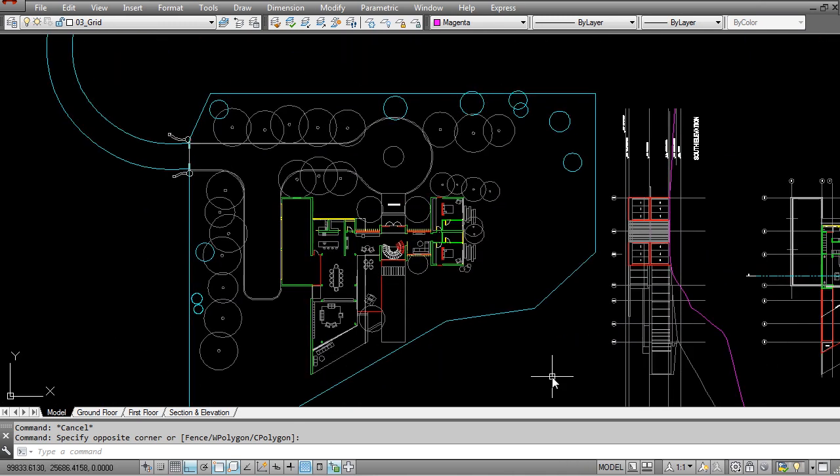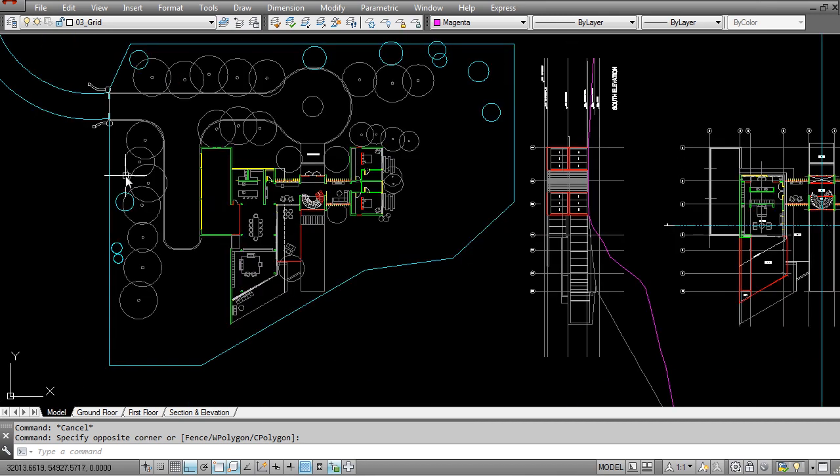So next you have everything else. Here you can create another split for yourself where you put all of your landscaping on a single ground layer and all of your furniture on another ground layer. It really depends on you as to how many subcategories of that ground you want to have. Obviously you don't want to fill up your entire layer manager in 3D, so just keep that in mind as you are doing this relayering process.